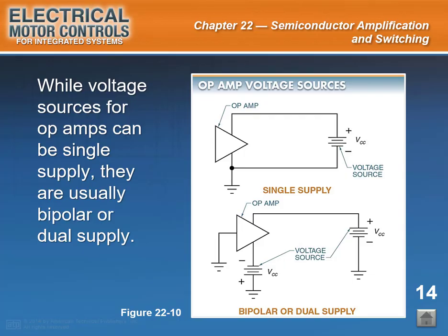See Figure 22-10. Like other solid-state devices, integrated circuits, known as ICs, need DC operating voltages to make them work. The DC voltage pins on some ICs are labeled common collector voltage, as in the abbreviation V with a subscript of CC. Other pins are labeled input voltage, as the abbreviation V with a subscript of IN, or supply voltage, abbreviated as V with a subscript of SS. DC voltage ratings in IC databooks are labeled all three ways.